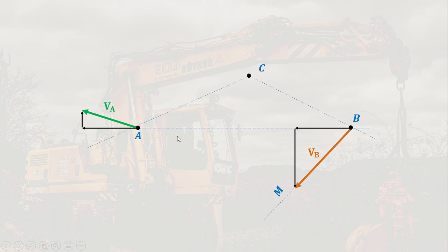So for C, we'll use this data now to get the absolute velocity of C. First we're going to resolve again the absolute velocity of B into two components, one that is perpendicular and one along the line joining them with C. As you can see here, this line BC connects B to C. The component of VB, the velocity of B, that is perpendicular to that line is this red line here.